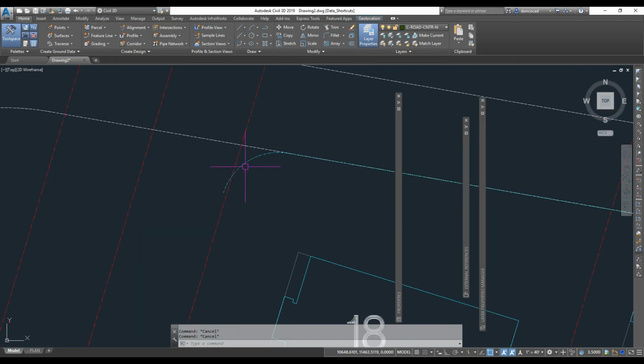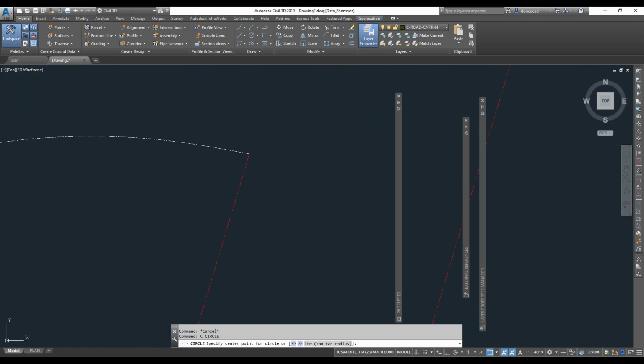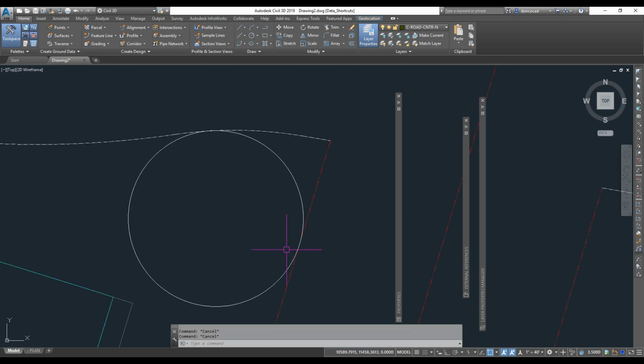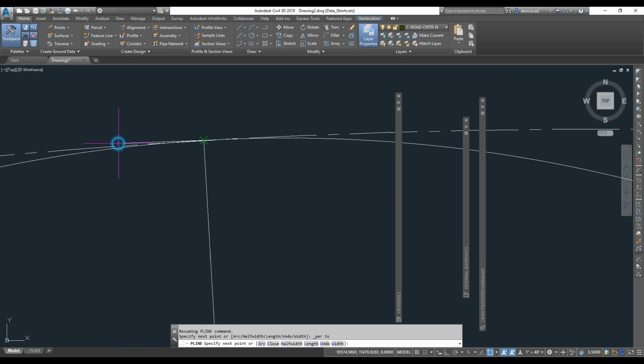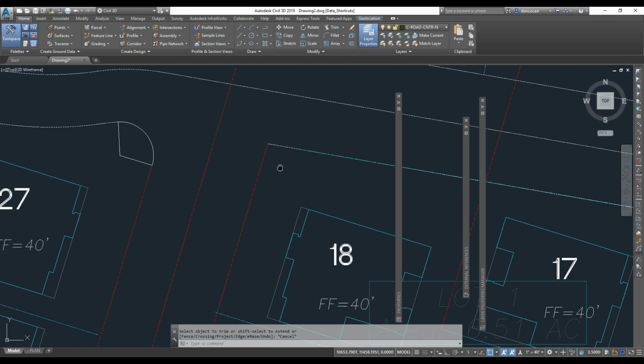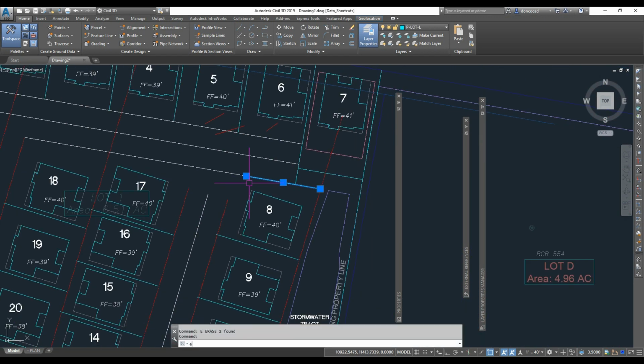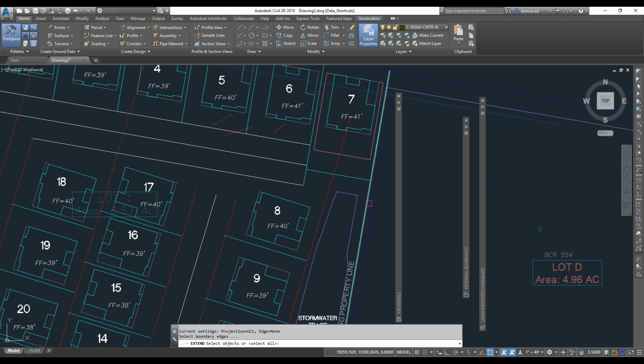Yeah, and then just keep cleaning up our intersections. And I'm a little bit old school. I like to draw the geometry, so I have an actual physical radius point. So I usually do that in all my intersections. You'll see that. So I'm going to finish up this geometry and then come back, and then I'll meet you with the corridor.